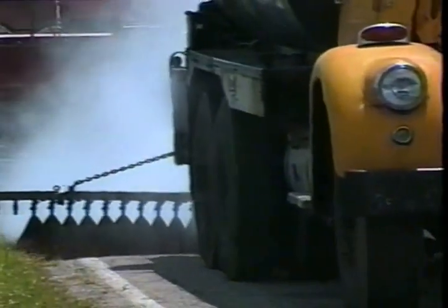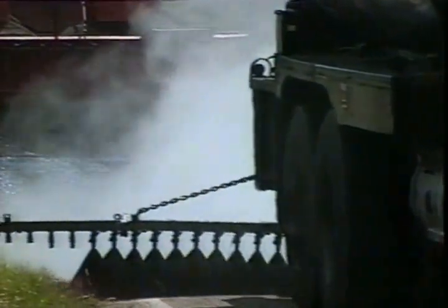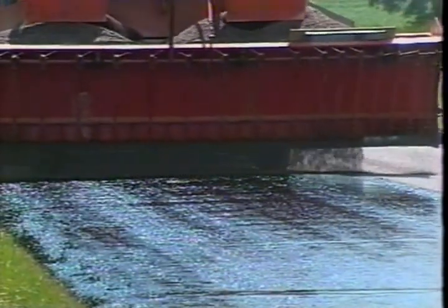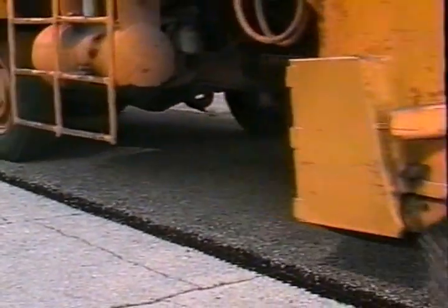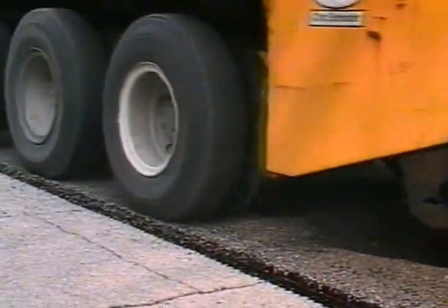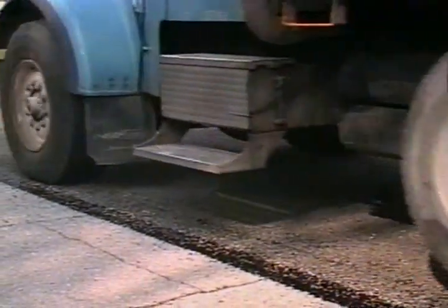The same procedure should be followed when asphalt cements or cutbacks are used, because it's almost always best to run a tight operation. That way there's less chance of traffic driving on the oil. With rare exceptions, the chip spreader should stay within 30 meters of the distributor. Regardless of the type of oil being used, the speed of the operation is important. If it moves too fast, the chips will roll when they hit the surface. The problem then is that the chip's exposed side is sticky, so they'll be picked up by the rollers and by traffic.